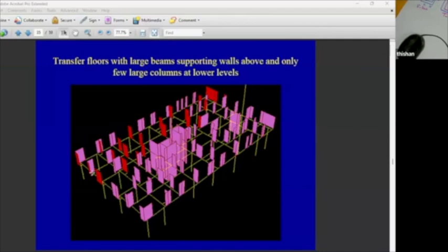On the software, we have to define the material. So define a different material. Transfer beam, zero density. Transfer beam normal, transfer beam zero density. So do two different materials. Property wise the same, except the weight, because now in the model we are adding additional members.